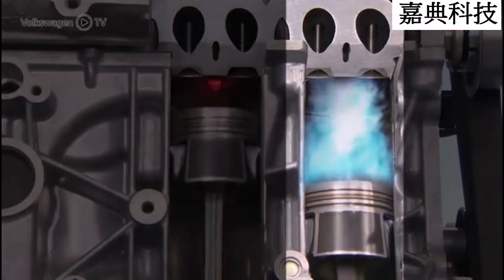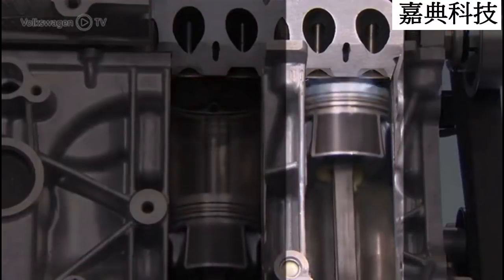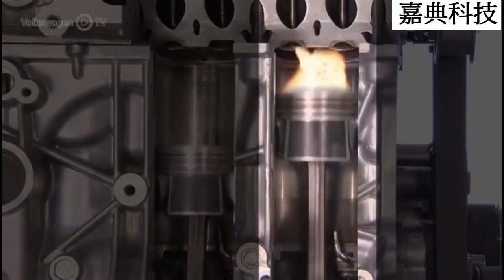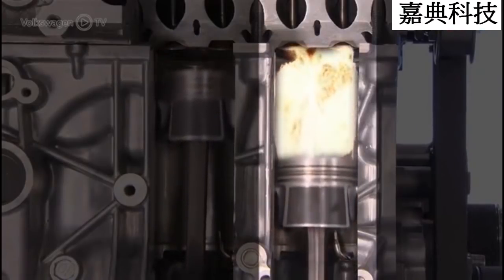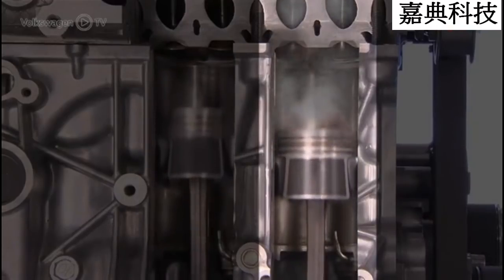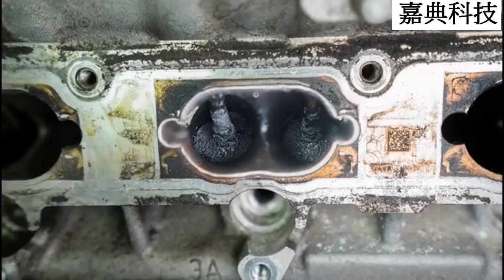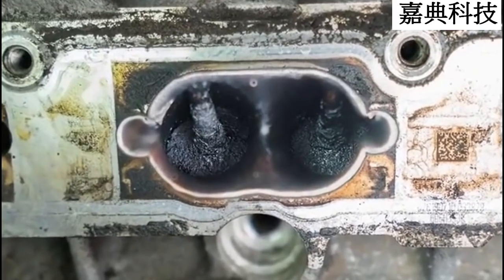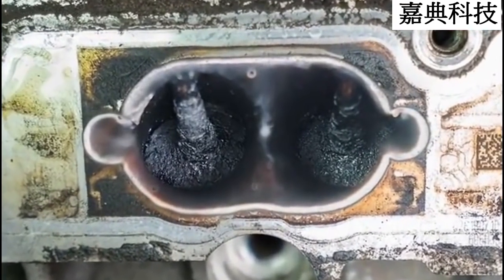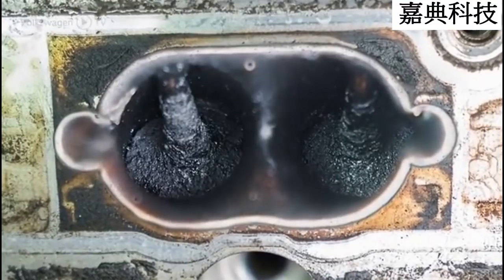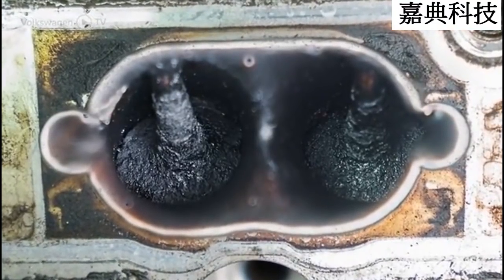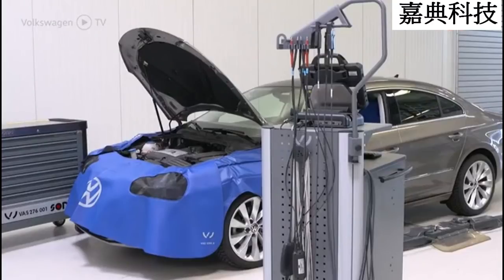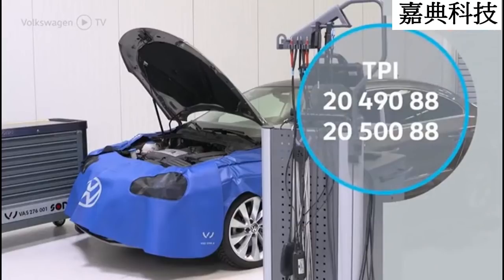However, engines with direct petrol injection do not have this cleaning effect. Their inlet ducts are only streamed by intake air and the engine's blow-by gases. This can lead to the inlet ducts and inlet valves becoming coked. These deposits impede combustion because they reduce airflow. For more information about affected vehicle and engine types, refer to the relevant TPIs.